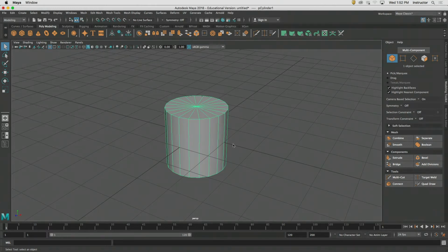One of the both good and bad things about working inside of Maya is that object history. You probably saw this last week when you were working on your wine barrel. Where do I go inside the interface to access my object history and to make changes to some of the properties and attributes of this object? Does anyone remember? We can go to the attribute editor.